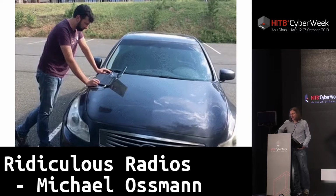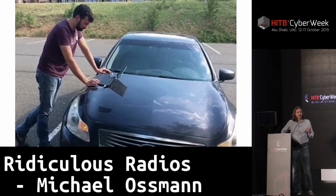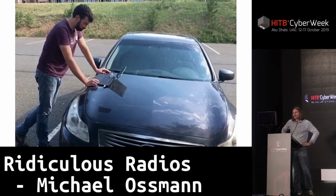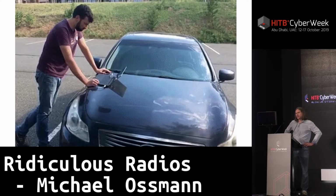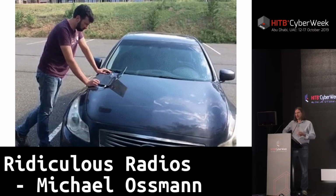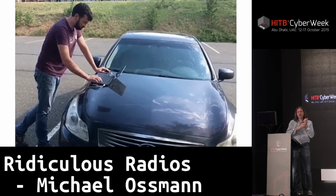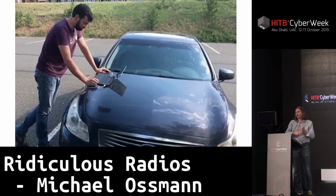Now, this happens to be a car that uses a remote keyless entry key fob that transmits frequency shift keyed data. And so we were able to successfully transmit this thing. And this demo was a little bit tricky to get working the first time because on a system like this, you have a rolling code. So the key fob generates a new code every time you press the button. And if you hold down the button, it should just keep transmitting that same code over and over again. But as soon as you release the button and then press it again, it generates a new code.